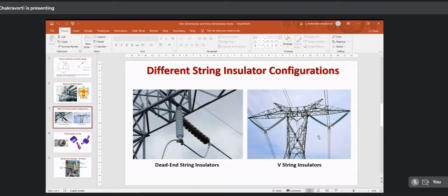Secondly, for repairing, you always have to keep such conductors in your storeroom. That's a lot of money in your storeroom. But these are very normal conductors used everywhere. So if one conductor goes wrong, I will just bring any other conductor and replace it. That's a big advantage. So we increase this effective diameter by using this bundle conductor.